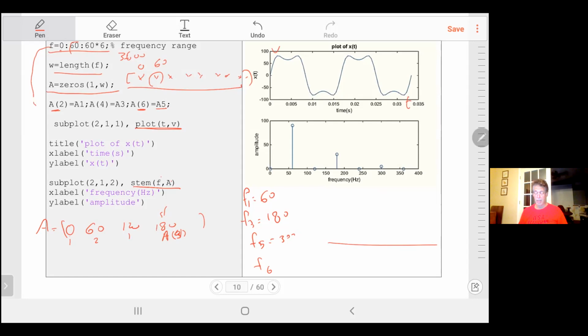We agree about that. Since we are going to divide the screen of Matlab into two, you want to sketch them on the same screen, so I divide the screen like that. So how many rows? 2 rows. You say subplot 2, that's 2 rows. 1 column, they are on top of each other.